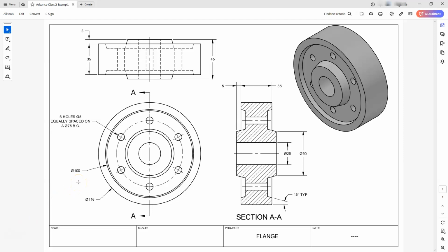So the most important thing that I want you to remember is anytime you have a cylindrical part that looks like this, you're going to always think a revolve command. And I don't know how else to say this, but when you're creating a revolve command, you're going to make a half of a half, if that makes any sense to you. So basically what I'm trying to explain is that half of this shape is going to be what I'm going to create. So I'm going to create half of a half. So you can see in the section view, this is half of that view cutting through. But I only need to create this top part.